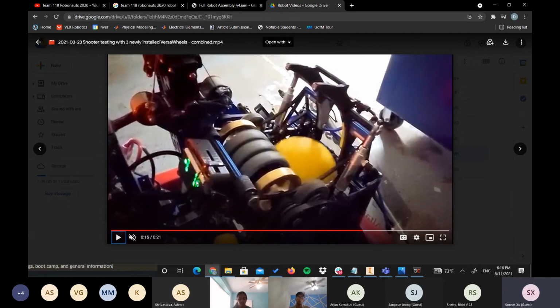And for the flywheels, we have 3, and we also have these little gold brass pieces on the side because a huge problem when we're shooting balls in real life is that there's friction, and when you're shooting at high speeds, there's a lot of friction. So we try to make the flywheel as heavy as possible, so every single time that we're shooting a ball out, our flywheel won't slow down substantially and change the trajectory of the ball. To make sure that everything's really uniform, we always try to make the flywheels as heavy as possible. So our flywheel mechanism is a couple pounds. It's pretty heavy.